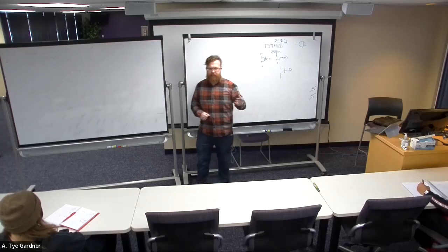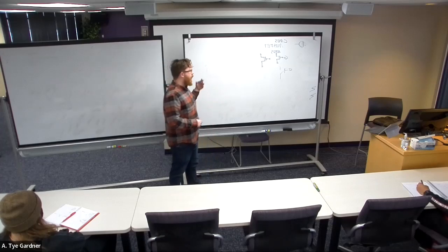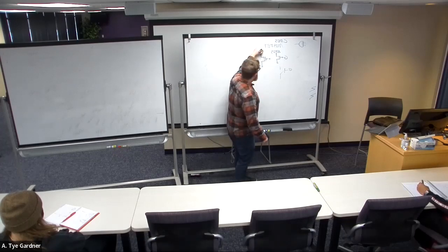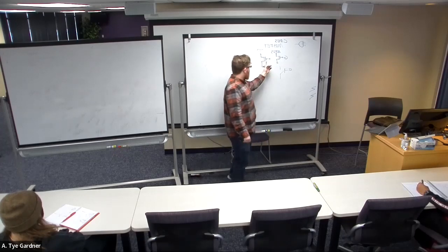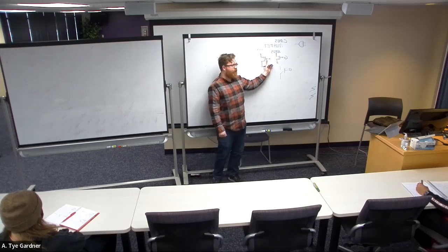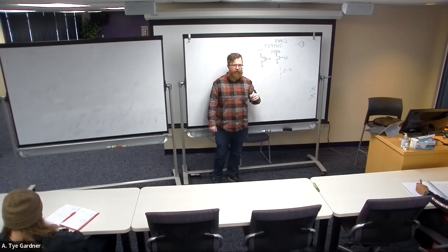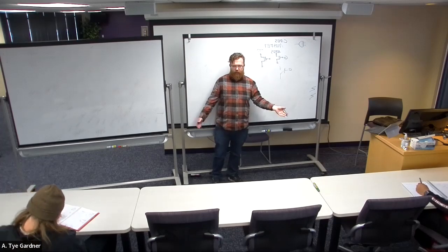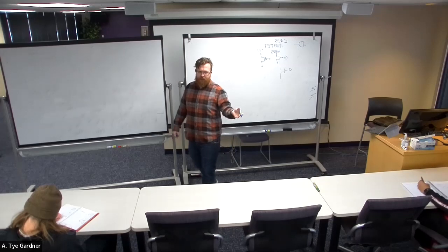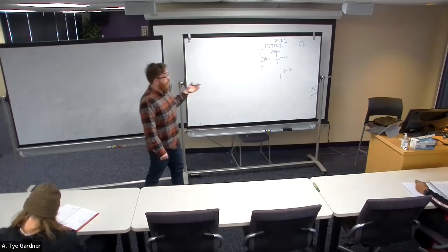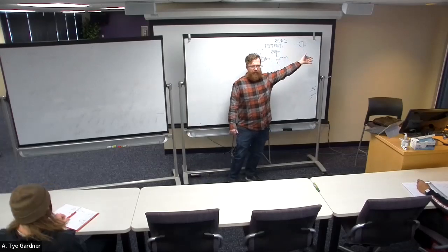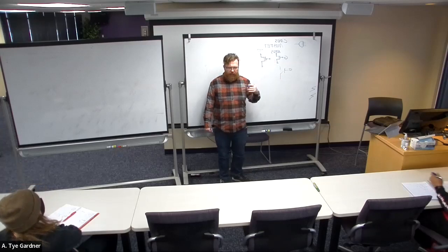Back to the CMOS idea, the C in MOS just means complementary MOS. Well, complementary because this is still the gate of the PMOS device, right? This is NMOS, this is PMOS. See the little bubble? This one is an inversion bubble. What this means is the PMOS device closes its switch when it sees a 0. So it's just negative logic, right? Active low circuit. And we've talked about active low. We don't do a lot with it in this class. We use it as control signals. But when we start looking at the innards of our AND gates, for example, these devices are what's in them.